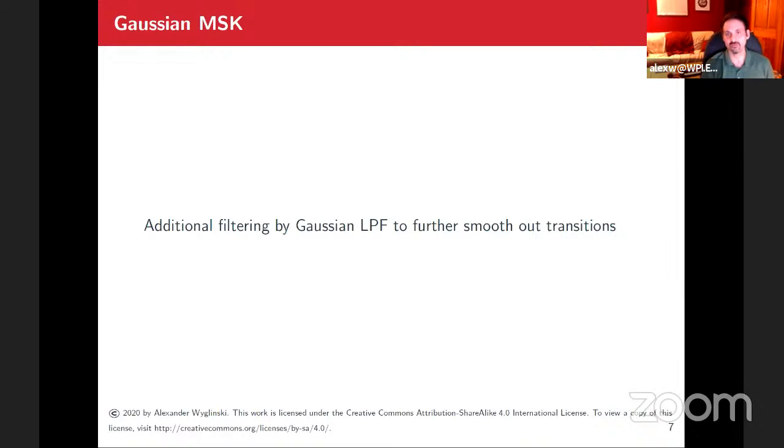But in essence, just remember, it's like half cycles of cosines and sines. You subsample your data stream into I and Q, right? And you shift by 1 bit period. And you start multiplying every one of those half cycles by either a plus or minus 1 amplitude. And what's attractive again is, because it's half cycle, it starts at 0, ends at 0, and has a positive value. And you either get a positive half or a negative half of a cycle, and then you modulate it. And what happens is that carrier frequency is always forced to 0 at multiples of 2 TB. And that, folks, is very, very amazing.